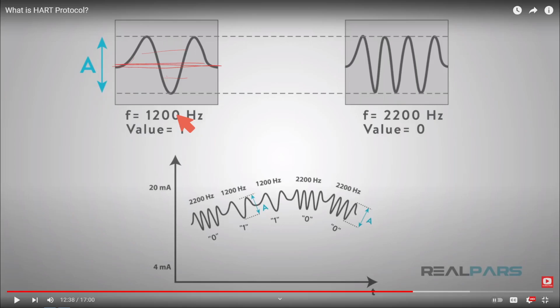So again, we just talked about pulse width modulation and how we're averaging it. Well, the same thing is happening here. We're averaging. We're at 1200 hertz, that's 1200 times per second, this is going up and down. So because of that, we are averaging out back to null, zero. So whatever the carrier voltage is, which is going to be somewhere between 0 and 24, or 48, depending on the signal type. I don't know what these are, but we're doing 4-20 milliamp signals.